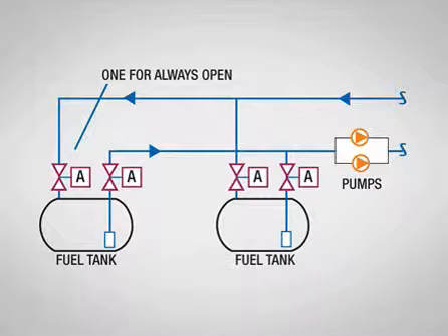There is a danger in multi-tank systems of drawing from one tank and returning to another tank, causing an overflow. This danger is particularly acute for continuously circulating systems, such as boiler feed or filtration polishing systems, where small leakage rates through valves can accumulate into large crossflows.